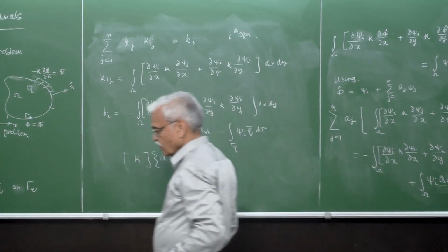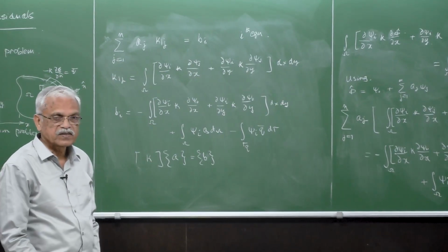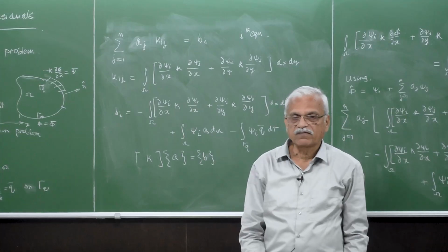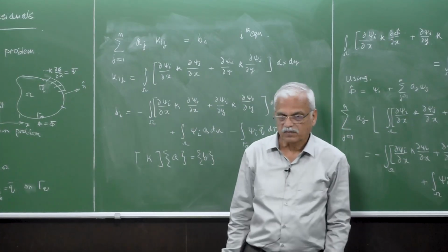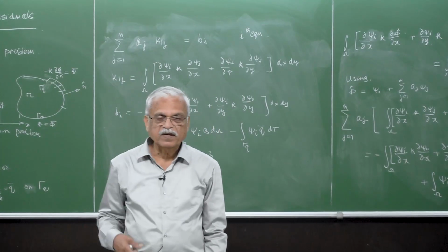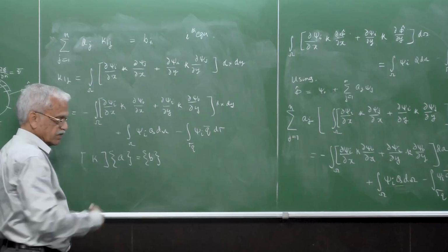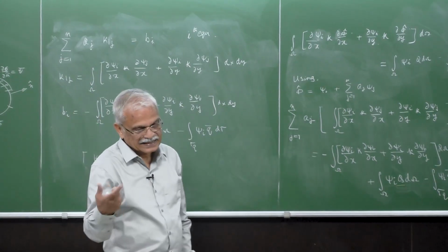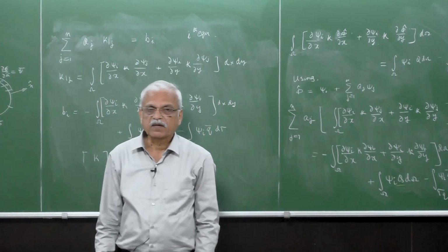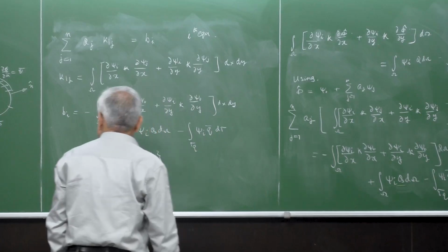This offers a tremendous advantage as far as our computations are concerned, because the storage roughly becomes half, and there are very powerful algorithms which can handle the inversion or the solutions of symmetric matrices. If you use this, the amount of time taken for solution of symmetric matrices is just 1/6 or even 1/8 of that for a fully populated K matrix. And further, of course, there are also other advantages later.